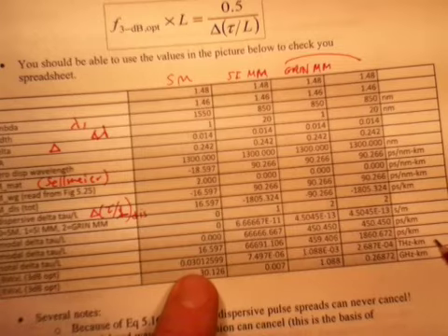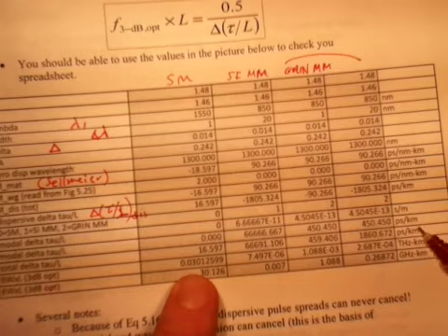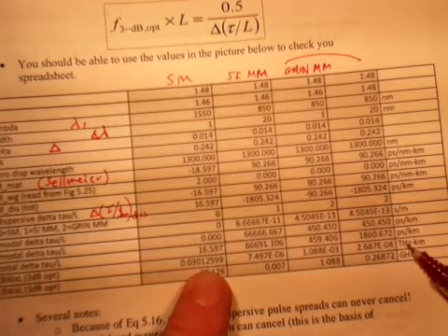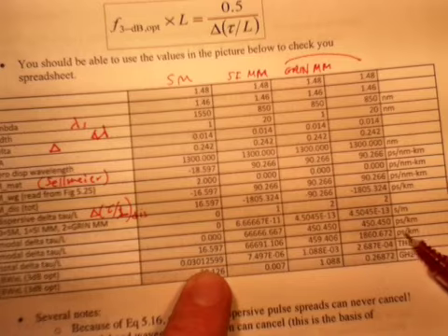Finally, I'm simply using the equations for the bandwidth distance products, and again, the units are tricky on these things. If you use picoseconds per kilometer, you're going to get terahertz per kilometer as the units, because picoseconds is 10 to the minus 12th, terahertz is 10 to the plus 12th.